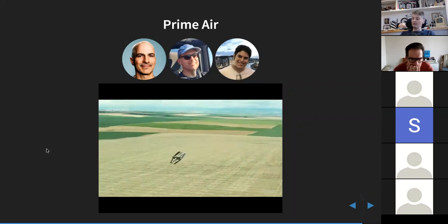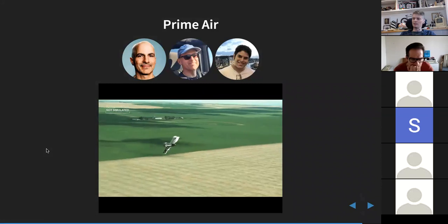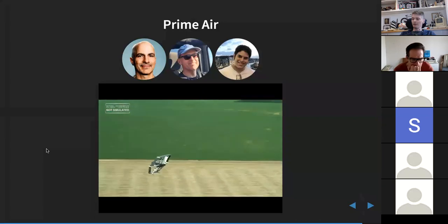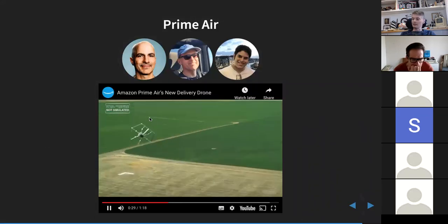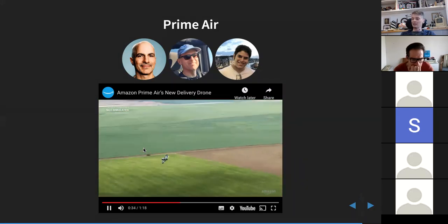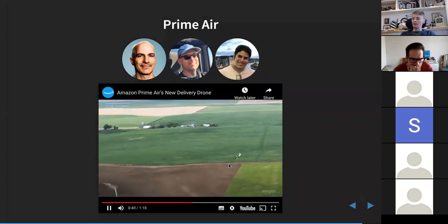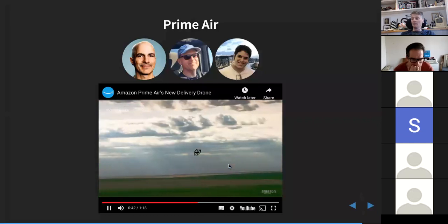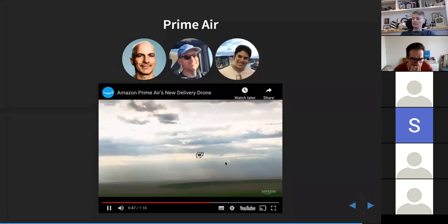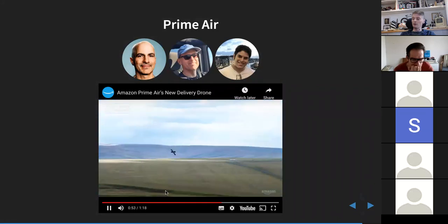And this is important. I've seen that they publicize these figures in the end. In order to make it productive, it has to have something like a 20-kilometer range on battery. And this horizontal flight it's doing now, these surfaces here are flight surfaces. The reason it looks so crazy, like a TIE fighter, is because the flight surfaces don't need to be as big as you would expect, because it's taking off vertically. Most of the lift you normally need in a plane is for takeoff. So it ends up with this ability to fly with very narrow control surfaces, which is the top and bottom. The other two things are shrouds and structural.